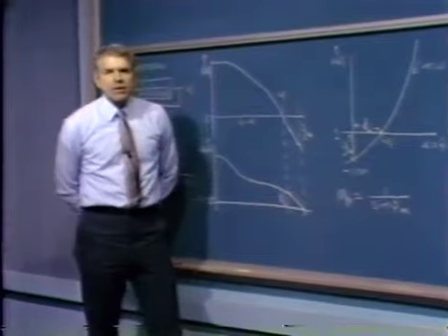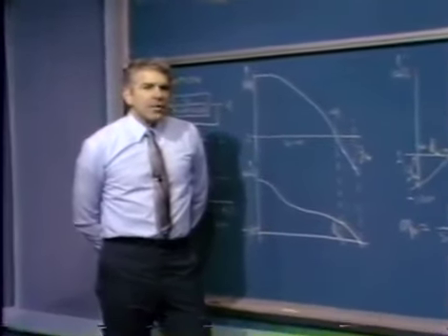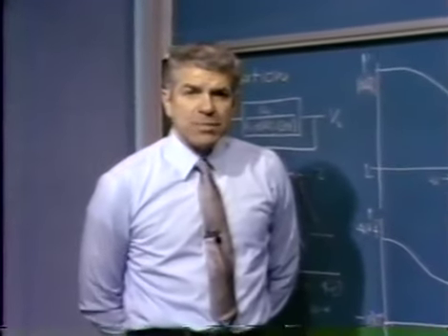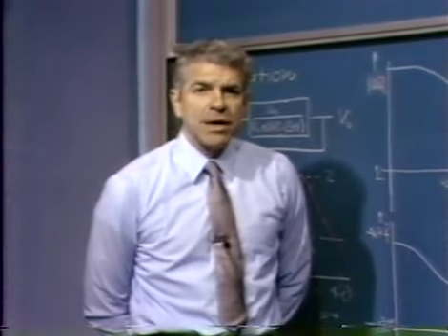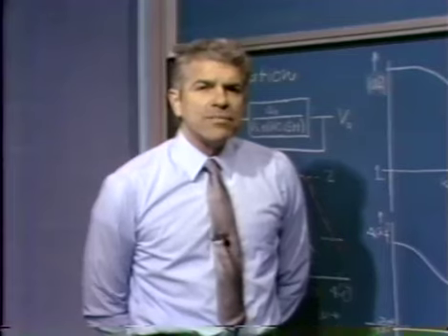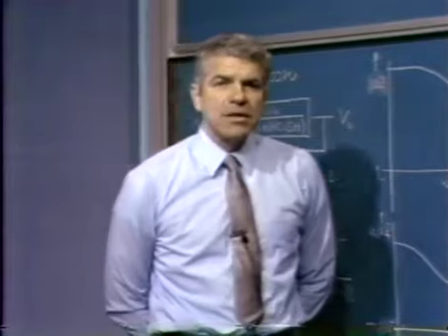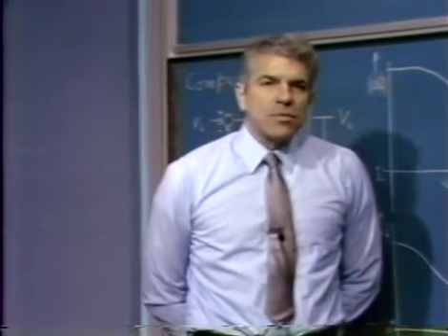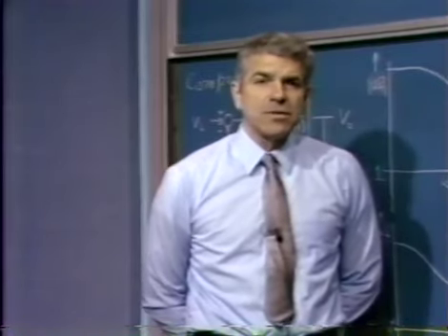Now the value of these quantities is that they very, very accurately predict important features of the closed loop response of the system. If we assume we have a topology with a frequency independent feedback path, the one we've been looking at in the Nichols construction, we can then get a very good indication of important parameters of the system by looking simply at these quantities. In general, the speed of response of the system scales directly with crossover frequency.